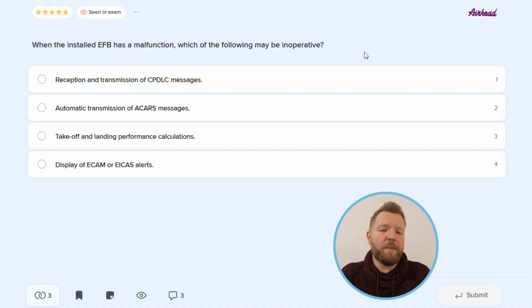One of these tools are performance applications that in a very easy and user-friendly way produce all the necessary information for the calculations. We simply have to select airport, insert runway, weather, aircraft's mass, and a few other important factors like, for example, intended configuration for takeoff or landing. The calculation can also take into consideration any malfunction if necessary. The result gives us, among other, speeds for takeoff and landing, so V1, VR, V2, or VAPP, flex temperature for takeoff, or stop margins for landing or rejected takeoff.